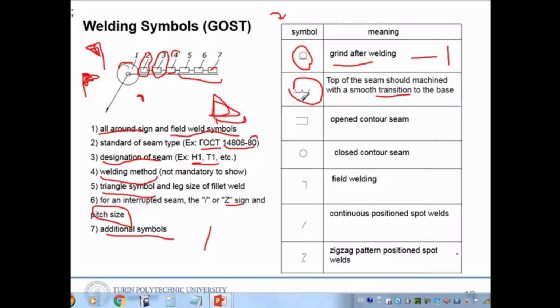You have to be careful when you are grinding, and when you are about to reach the original size, you need to make a slow transition. You have to slow down and be careful with the top of the plate.